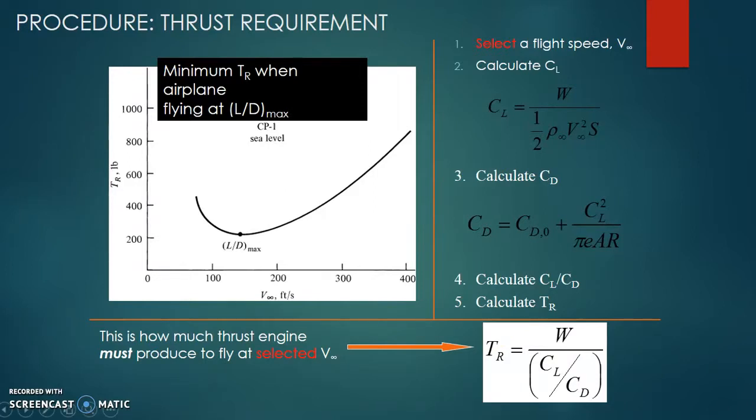Hence, aerodynamics plays an equally important role in the requirement of thrust. It also tells you that no matter what I do, I need a minimum thrust of this level to make a sustained flight, and at other lift conditions or at other velocities of flight, I need a thrust much higher. That's the requirement of propulsion.